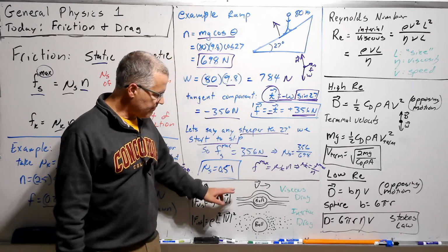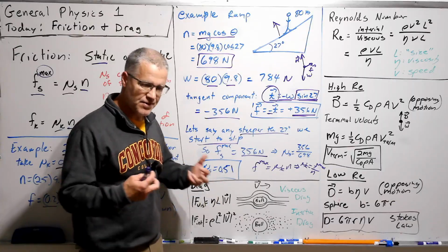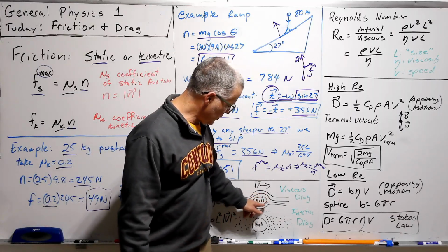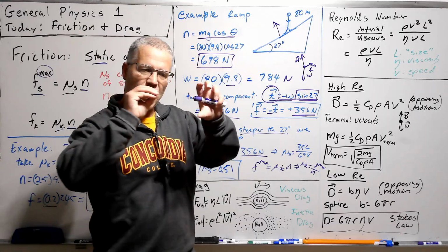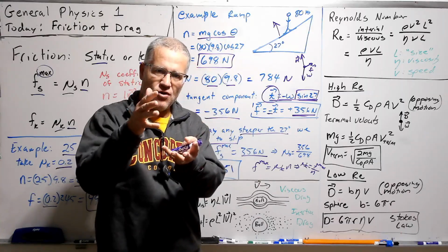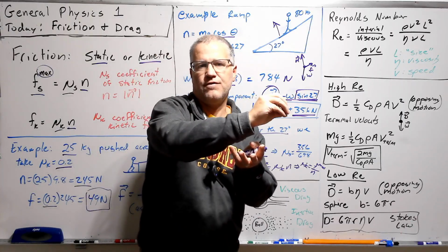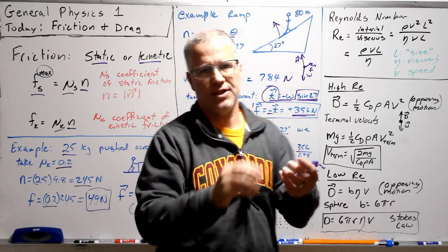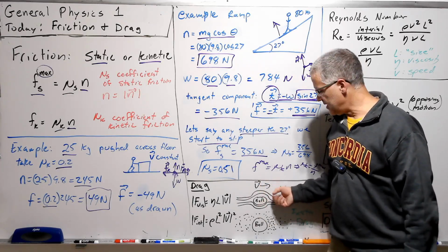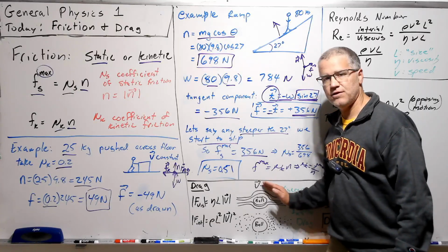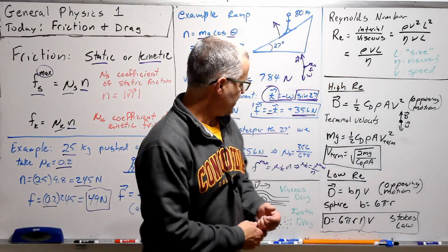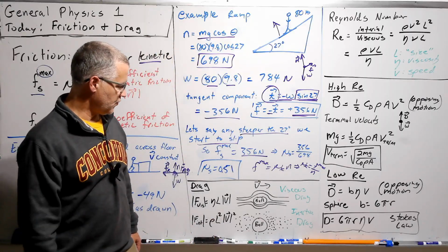And we have two components that make up the resistance to motion. One is called viscous drag. And if we kind of envision here, this ball has to find its way through so-called lamina of fluid. So the fluid has to flow around the ball as the ball moves through the solution. And there's a resistance to that called viscosity, a resistance to having layers of fluid flow at different rates around the ball. That's called viscosity. And so this is a viscous component to the drag.